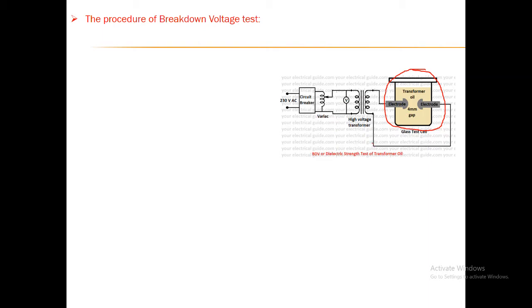If during the testing you find that there might be a problem occurring on the high voltage transformer side, then you have to isolate the source from the tested objects. To prevent unnecessary damage to this high voltage transformer under the faulty situation, a circuit breaker is provided.